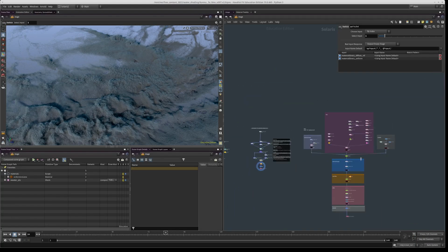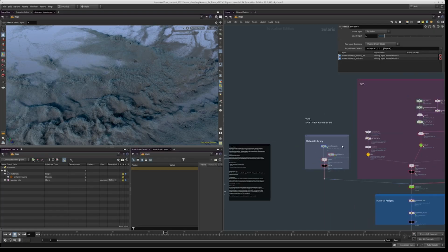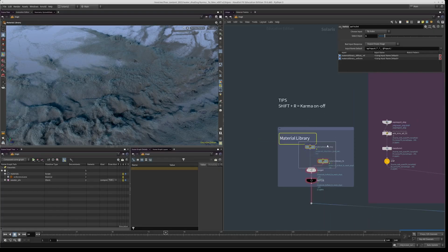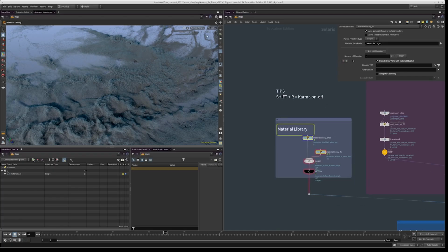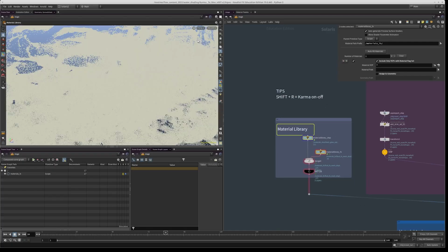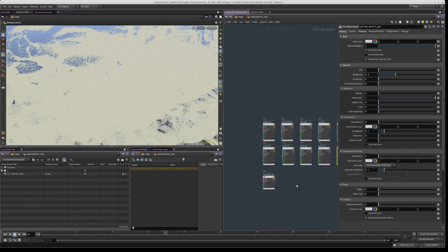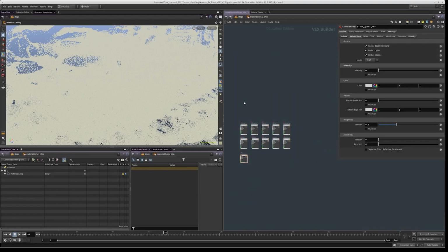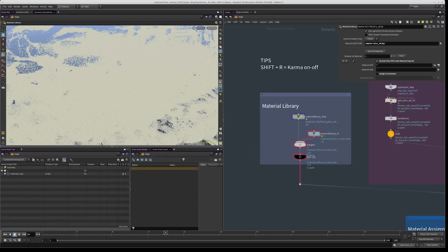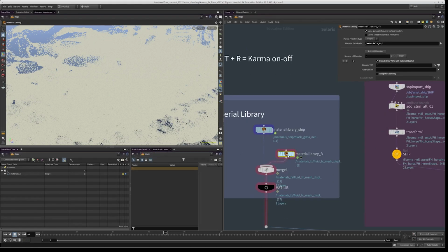So this is a more complex example. We're going to cover custom AOVs and Cryptomatte. That's why there are more things here. But we're going to go through it step by step, and I think everything is going to be clear. So we have two material nodes here just to keep things clean. Let me disable the rendering. So we have a ship shaders, and let me dive inside that. This is all just reading the specular texture, diffuse texture, and getting it assigned to the right meshes.